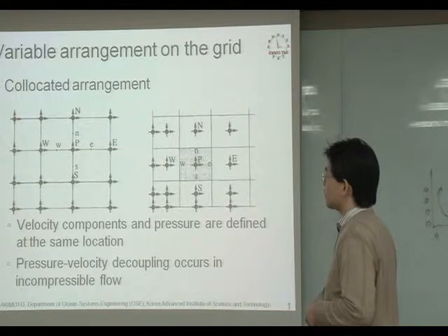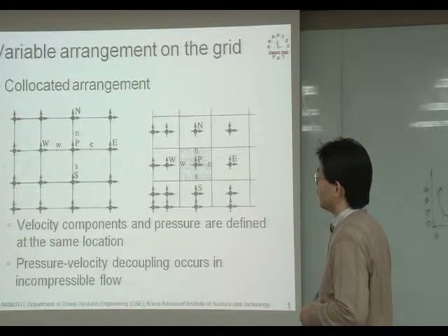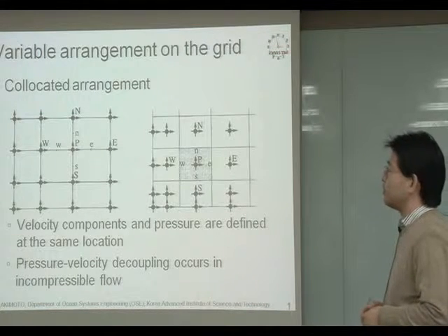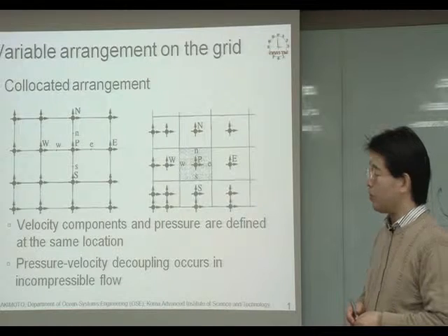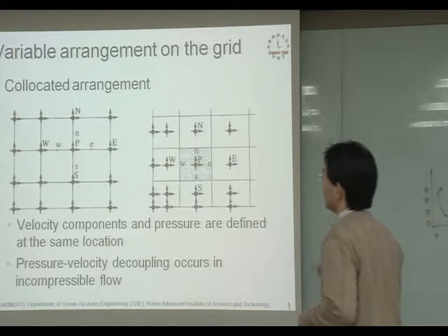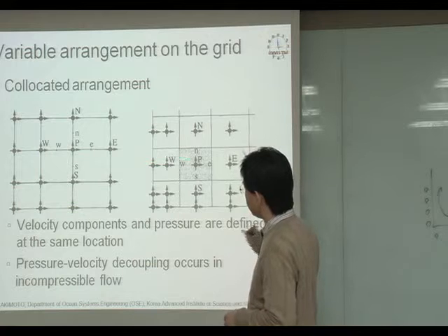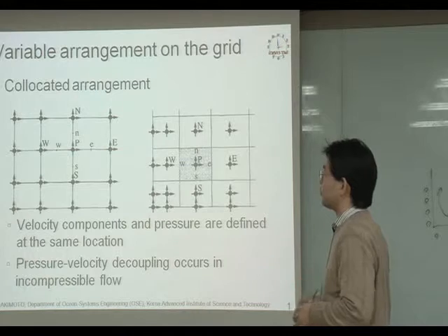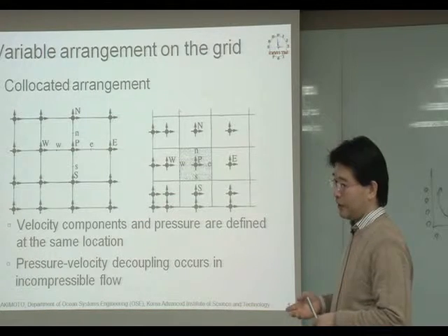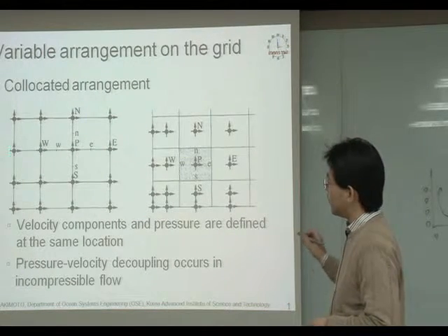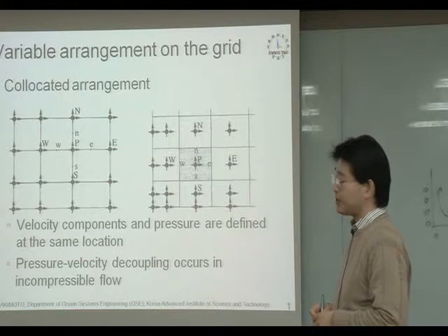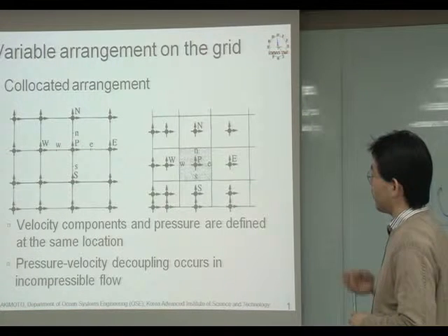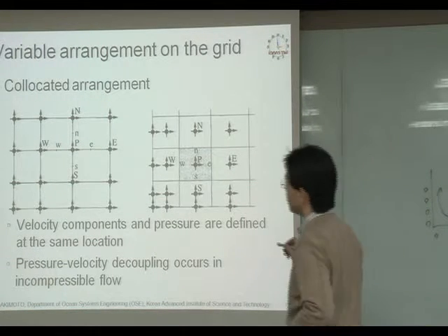This slide gives the information of why a staggered arrangement is used in incompressible simulations. Both these two pictures show the collocated arrangement. The left side one is for the finite difference mesh, FDM, and the right hand side is for the finite volume method.